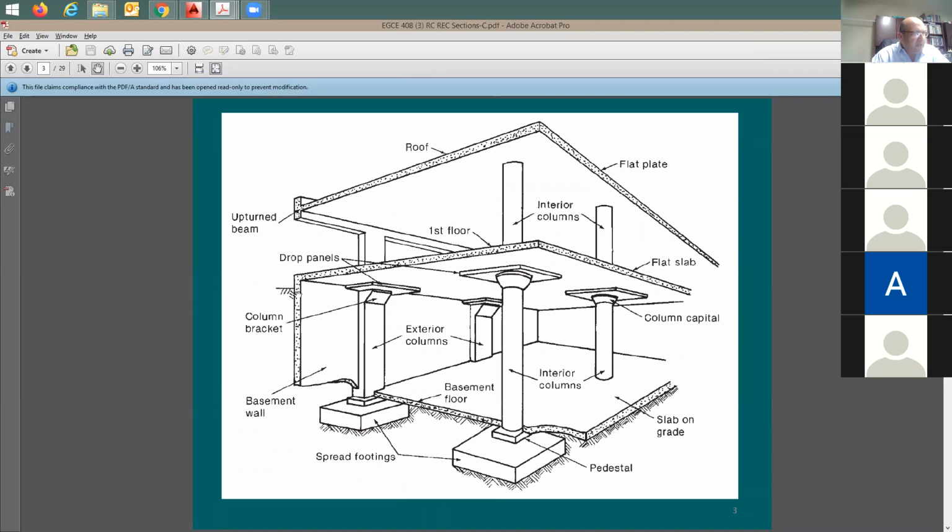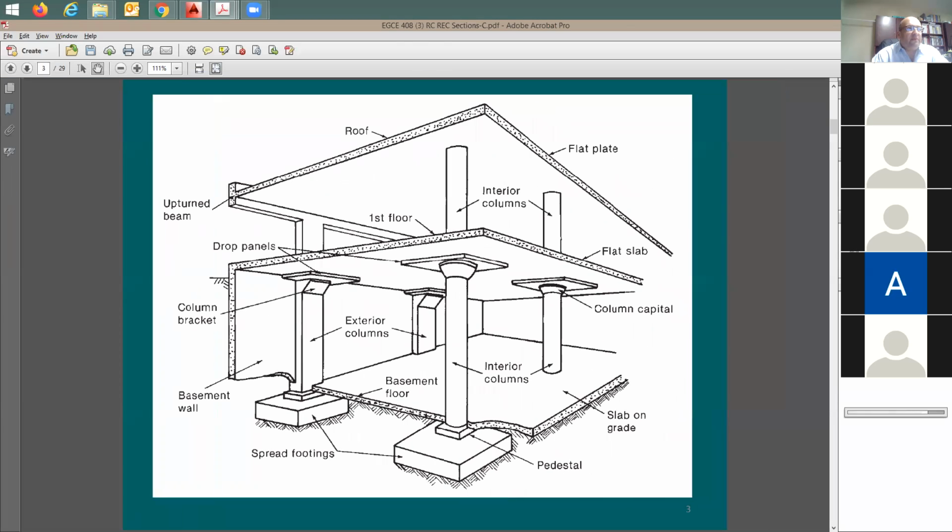So this wall here retains all the soil, right? But it is restrained at the top. If the soil pressure is pushing from this side to this side, it's going to be pushing to the inside. It's going to be outside of the building, and it's going to push inside of the building. And the soil pressure, as you know, is going to be modeled as maybe this hydrostatic pressure. I don't know if you guys have seen this or not, but we're going to be going through it. So in a case like this, the soil is pushing the wall, and the tension side is going to be inside, correct? So if I need to put reinforcement here, I'm going to put it mainly on the inside face, not the outside face of the wall.